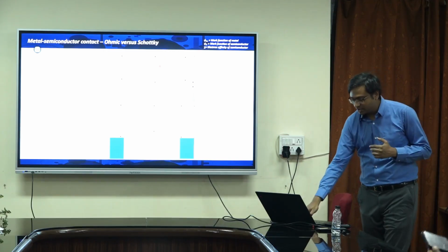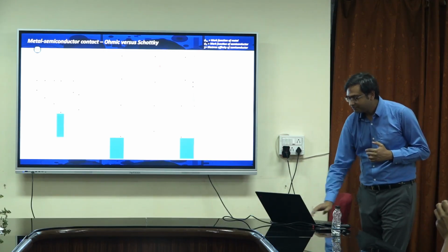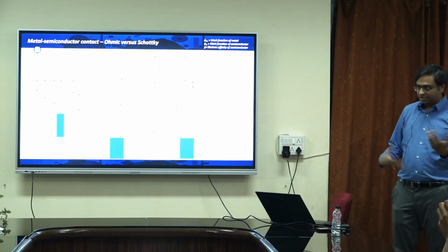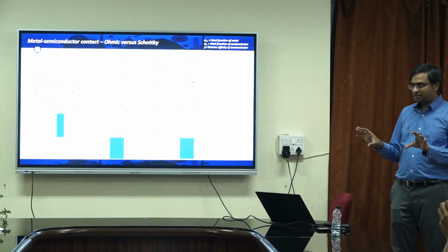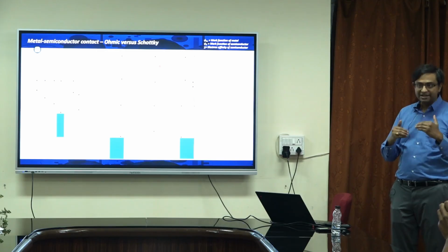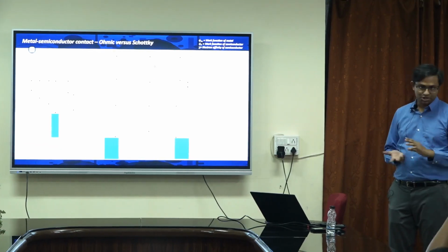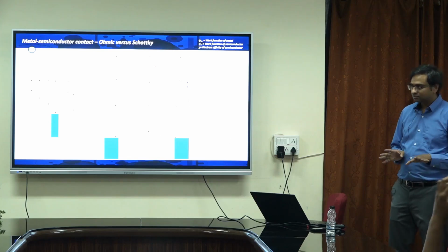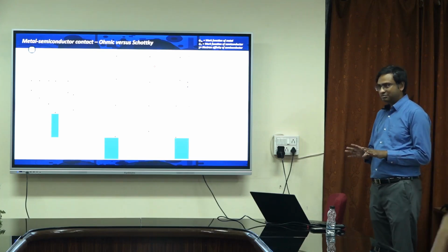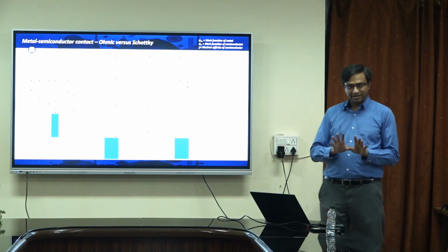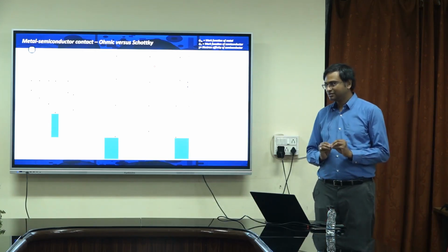And you can see by doing work function engineering, without changing the 2D material, by just changing the metal, I can get an ohmic contact or a Schottky contact. Make sense? Any confusion you have, ask me.